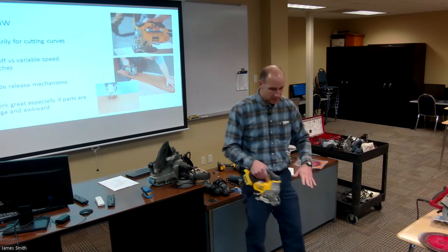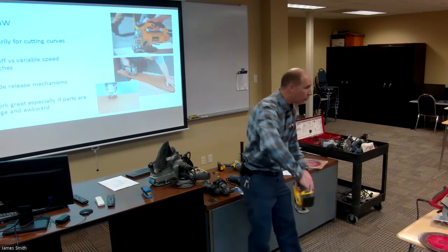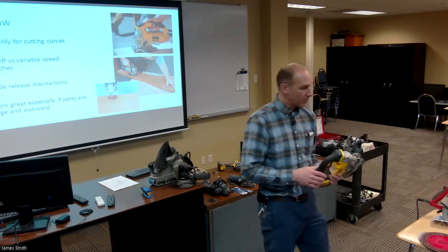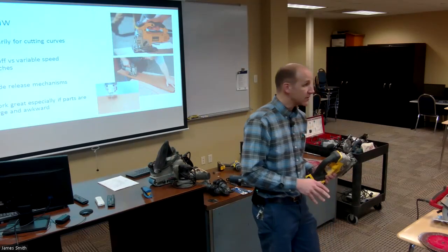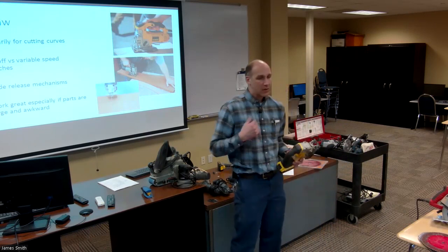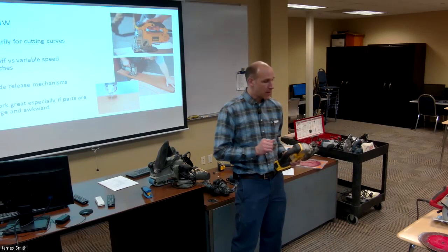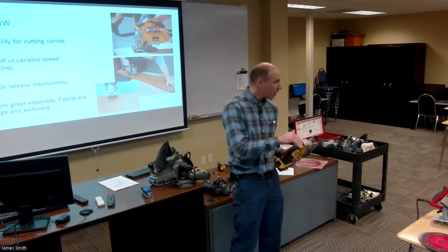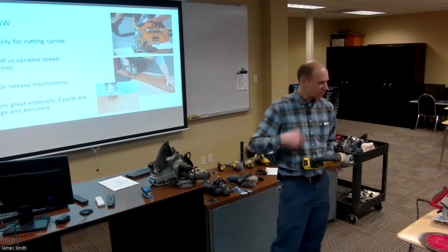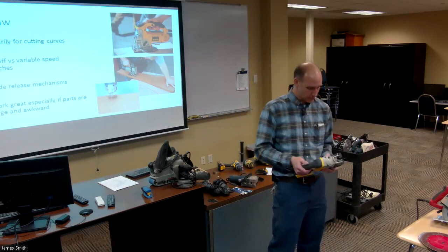It's nice because you can lay out your sheet, right, and then just kind of work the saw into it, and because it has a narrow blade, you can cut really tight radiuses. And for radiuses that are even tighter than what this blade would allow, you can do things like nibble cutting and cutting relief cuts and doing things like that. So there's a little bit of pre-planning that's required that way.